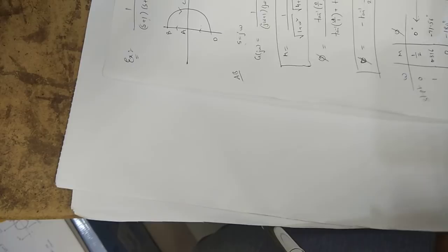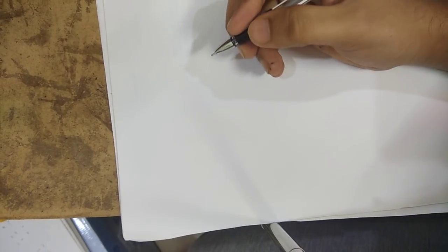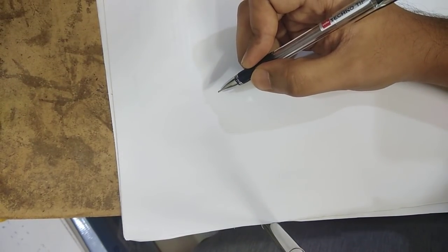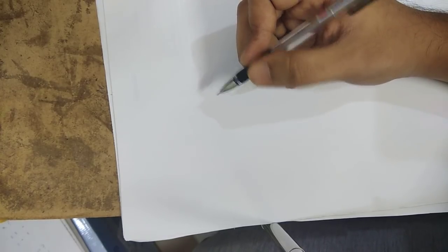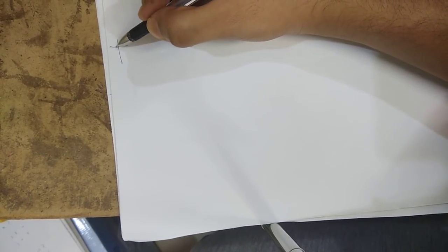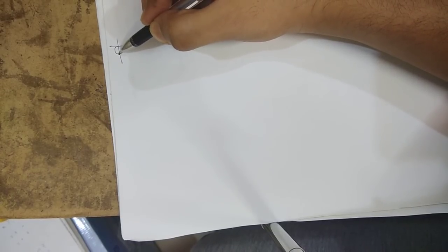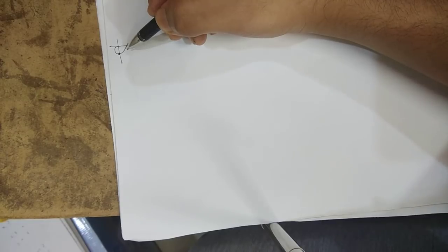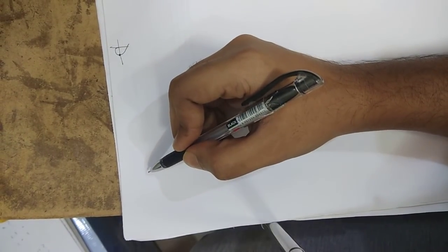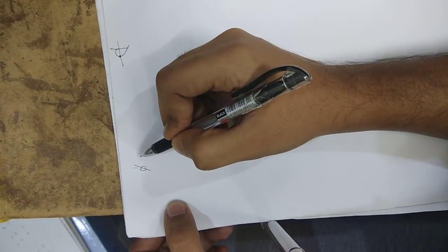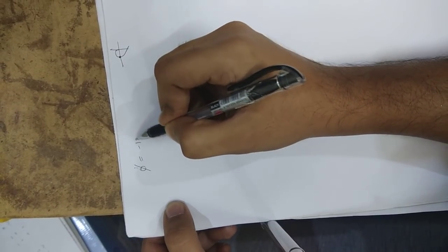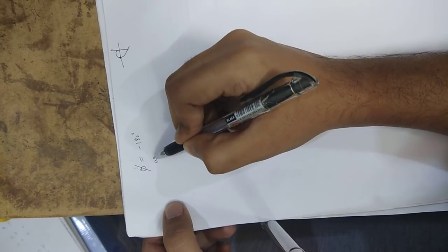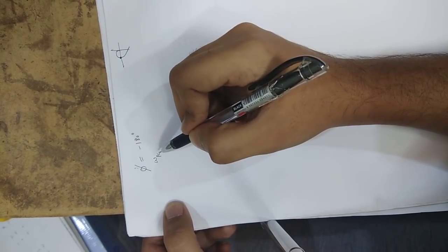And now let us do a little bit difficult problem, but there is one more small concept left in these plots, that is, what if there is an intersection across this x-axis? So how to calculate this intersection point? There is a method: we will find the phase of the system, phi. Now equate this phi to -180 degrees and you will get the value of omega. That omega is known as omega pc, the phase crossover frequency.